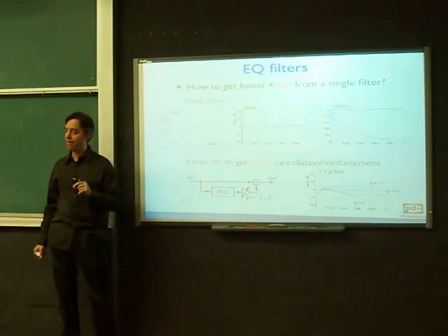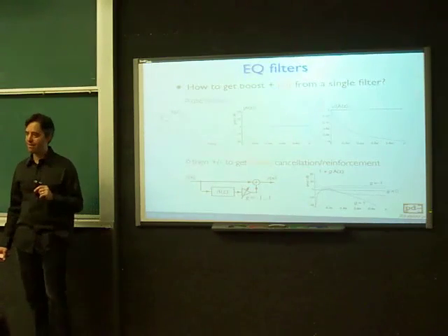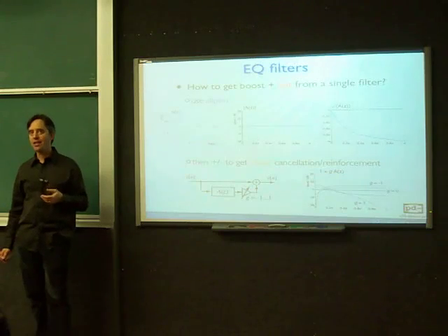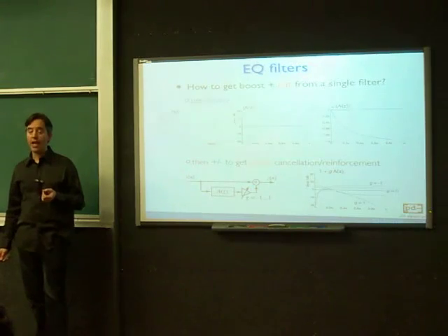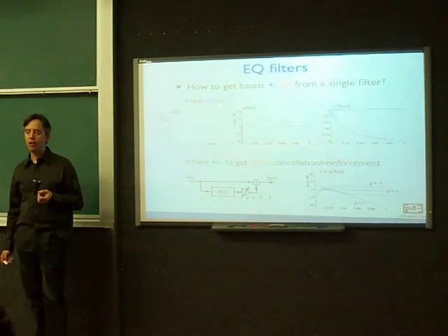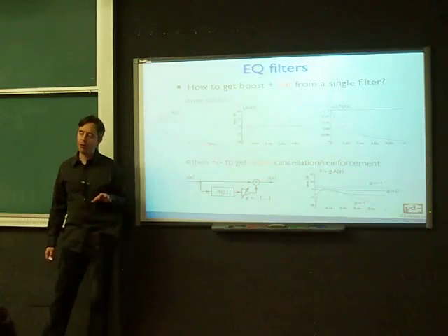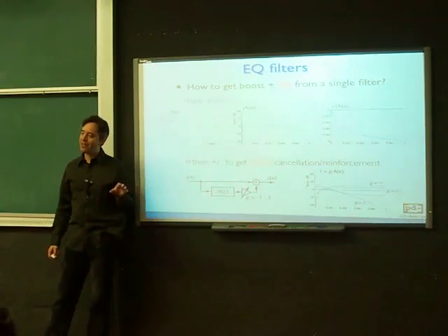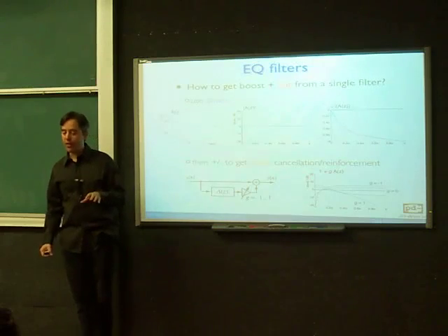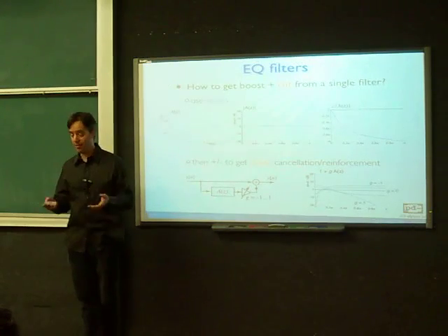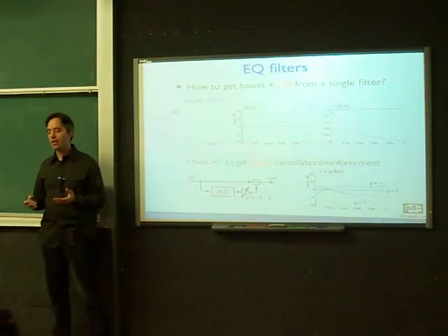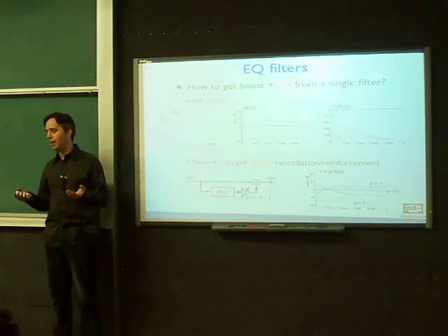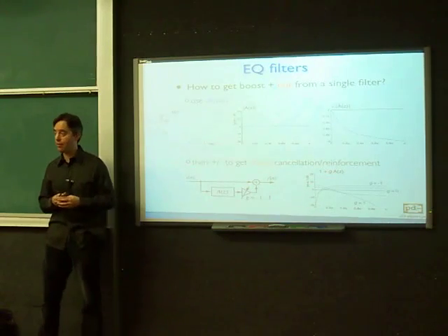Yeah? So nowadays it's mostly done digitally? Well, I guess in most cases it's done digitally, but that still leaves the question of what the algorithm is. I don't actually know, but the analog systems typically use mostly poles, and as you remember from DSP, a pole system is an IIR system, versus an FFT-based system, which is actually an FIR system. IIR systems are normally much more efficient; they use maybe 10 or 100 times fewer operations per sample to get what you want.